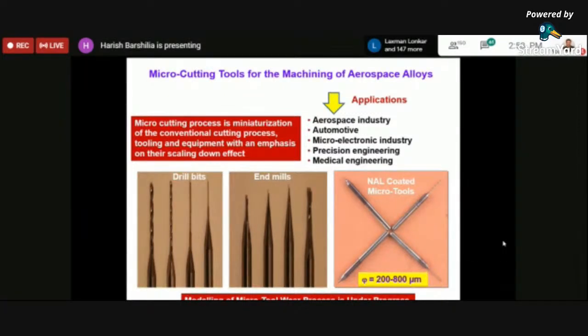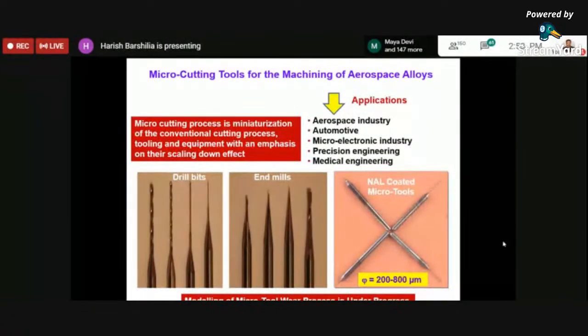Conventionally people have been using laser drilling, but laser drilling has a lot of disadvantages because there is a lot of heat formation and a lot of material buildup, and as a result a lot of stresses will be generated in the turbine, which you cannot afford because the turbine has to run for 25 years, and if there is a small amount of stress, it will grow over the years, and after some time it will fail. Which we don't want.